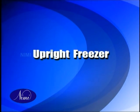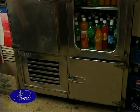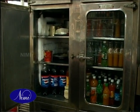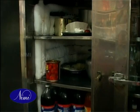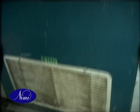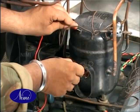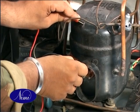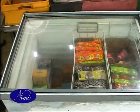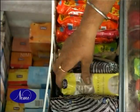Upright freezer. The basic refrigeration system is used on all upright freezers. The only variation being the use of a fan-cooled condenser located under the cabinet in a few models. Other upright freezers use a static condenser located on the back of the cabinet. All units are of conventional hermetically sealed design. Chest-type freezer. Ice cream freezers are similar in most respects to chest-type household freezers except for interior design.